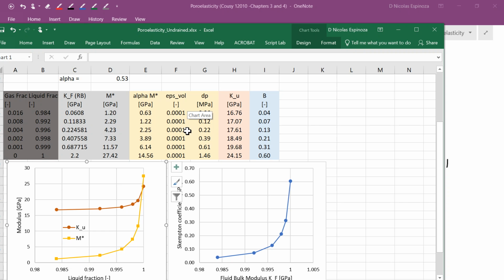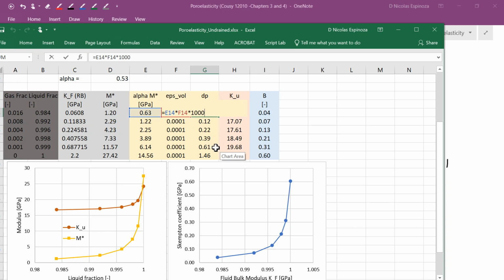So this is a very small strain, but even with that very small strain, according to the equation that we obtained, in which the change of pressure dP is proportional to the product of these two, we get that the expected change of pressure is relatively small when the fluid has a significant amount of gas, and increases as the gas starts to decrease.